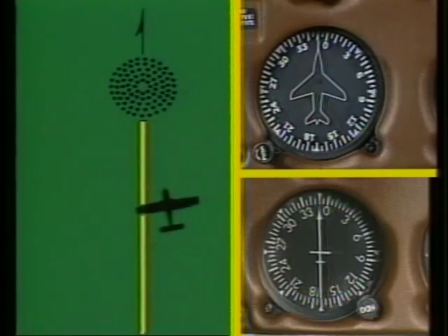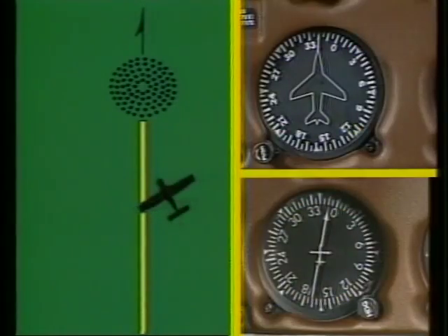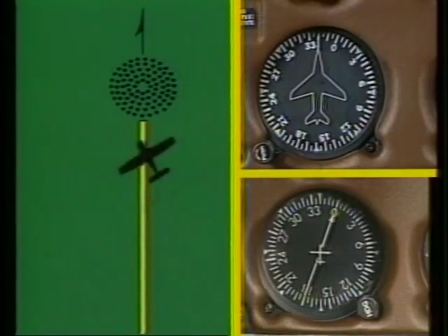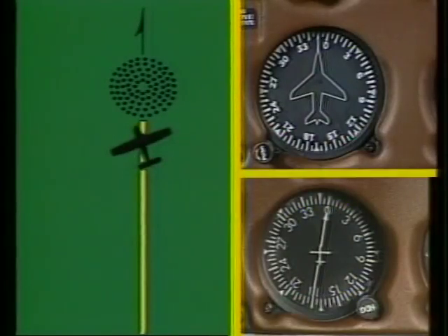you've corrected for the drift, but you will not intercept the 360-degree bearing. So, an additional correction is needed. In this case, you are using a 20-degree correction angle to regain the course. If you continue to keep the ADF heading aligned with your magnetic compass, you can verify that you have returned to the course when the head of the bearing pointer equals 360 degrees. To remain on course, use just enough crab to maintain this magnetic bearing.